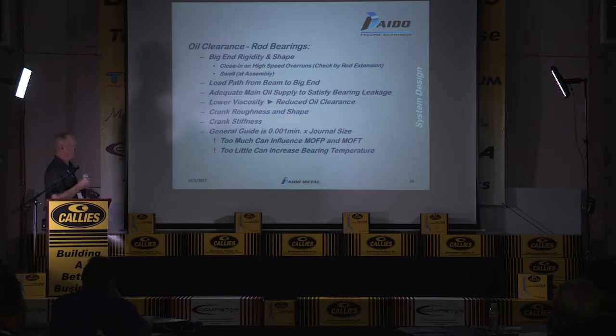If you remember the slide with the pressure profile, as you increase your clearance, that pressure profile actually starts to get narrow. And once that pressure profile narrows, then the load increases. And that's where you start to see some damage and other things.